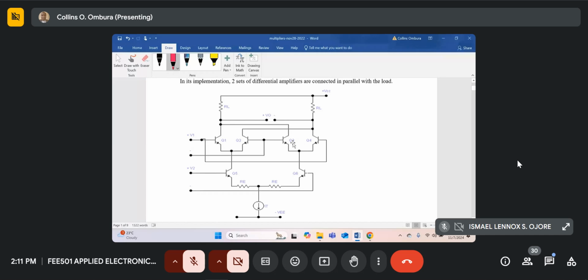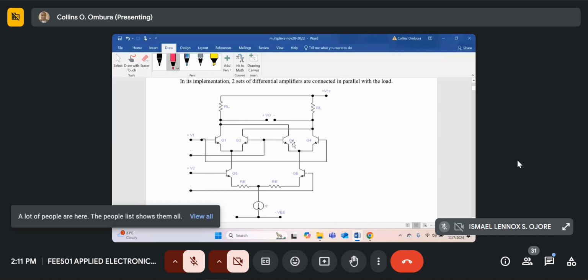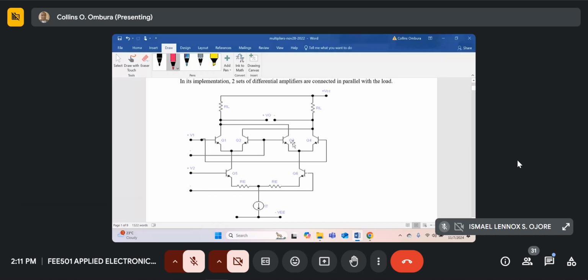And we considered the current relationship for any simple general differential amplifier. Notice minus GM12, where GM12 is the transconductance of Q1 and Q2, into V1, RL, and V naught is just a drop across RL minus a drop across RL on the right, in equation 5.